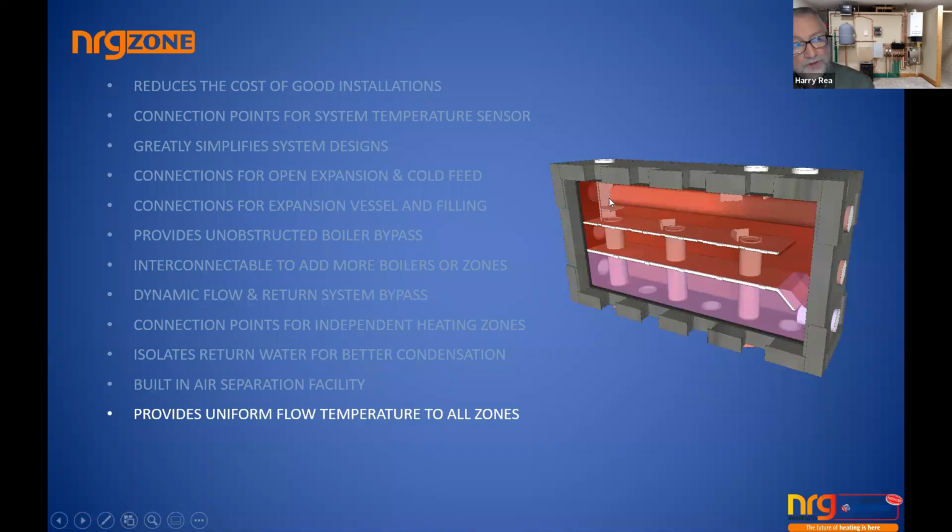And then you have a uniform temperature with every zone, because no zone contradicts any other zone or in any way influences any other zone. So each zone has equal access to the water if the water coming in is equal to the total amount leaving. And then the units come with inch thick, 25mm insulation all around when they're delivered, standard units.